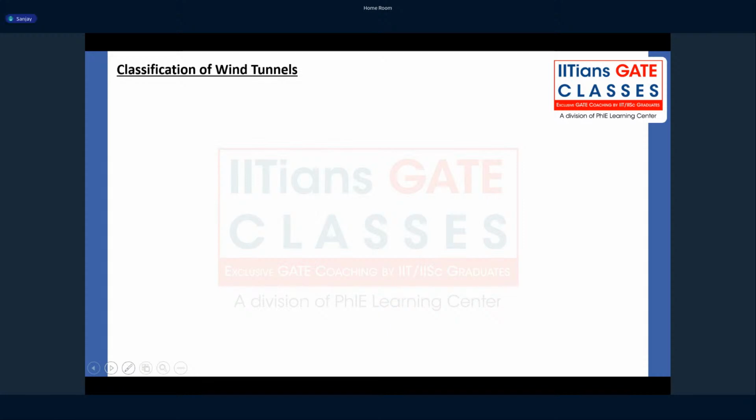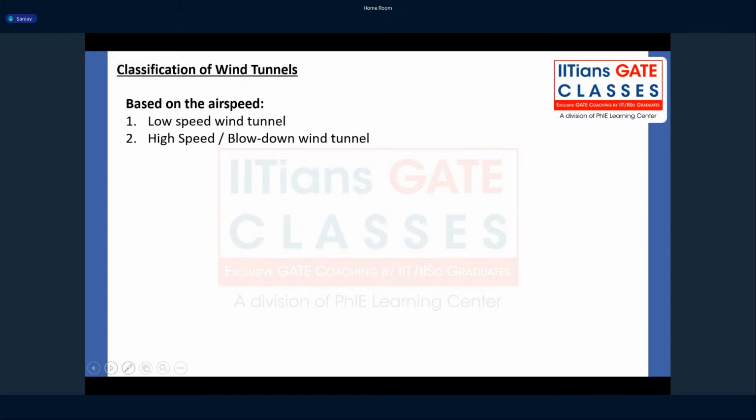Now, we can classify the wind tunnels into different types. So first, based on the air speed. So what is the speed of the air through the wind tunnel? Okay. And in what regime is that speed classified? So based on the air speed, you can classify the wind tunnel as a low speed wind tunnel or a high speed wind tunnel. Okay. Now, what is that clear demarcation between low speed and high speed? So generally, low speed wind tunnels simulate incompressible flow. So we say that the flow is incompressible in a low speed wind tunnel.